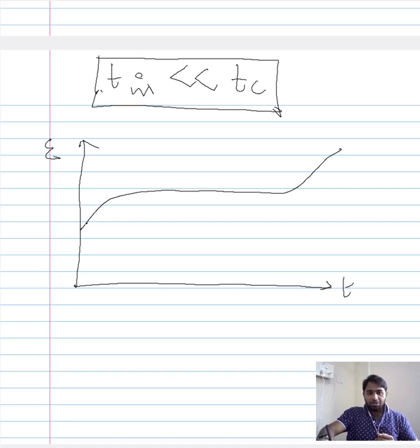Your curve begins with the transient creep region, then follows with the steady state creep region, and finally you have your accelerating creep region. So in that case, your stage 1 will exclusively comprise of the transient creep region. Depending on the time taken by your material for the instantaneous creep, the description of the stages varies, particularly the description of stage 1.